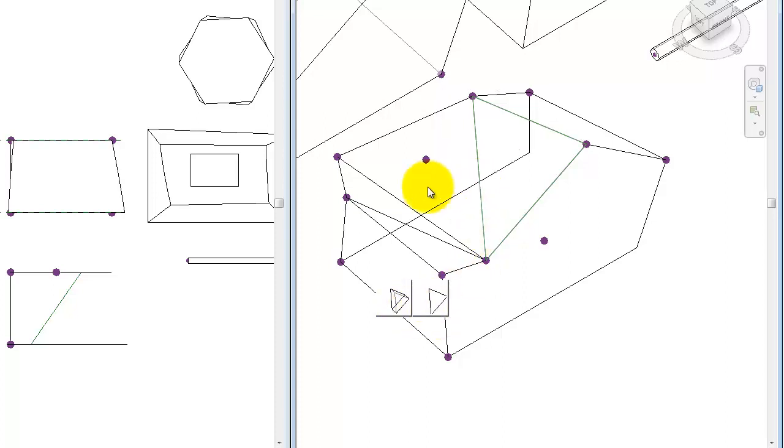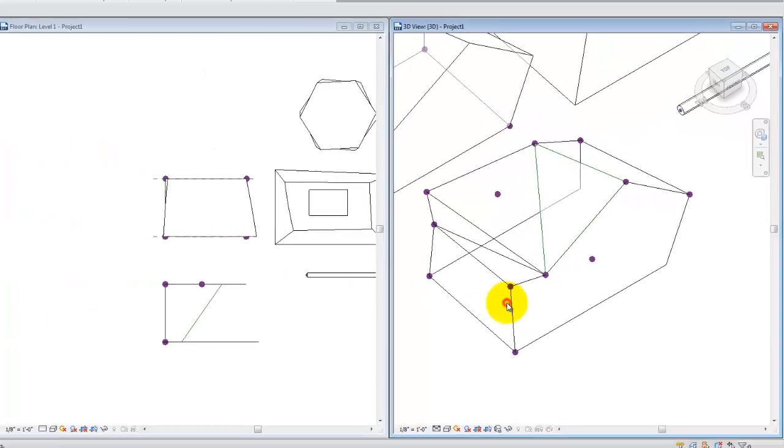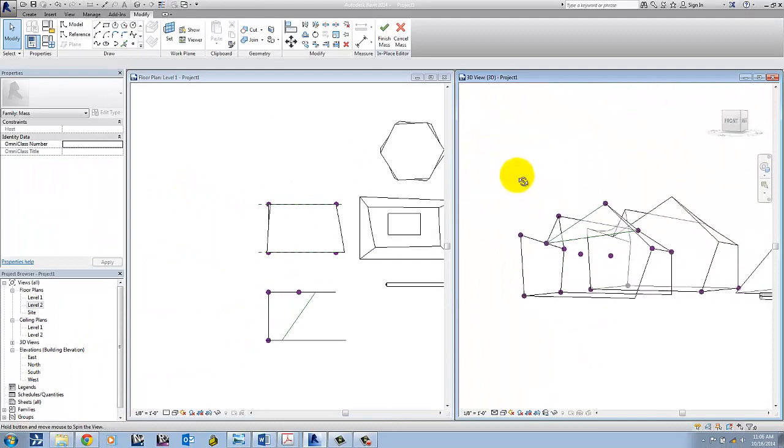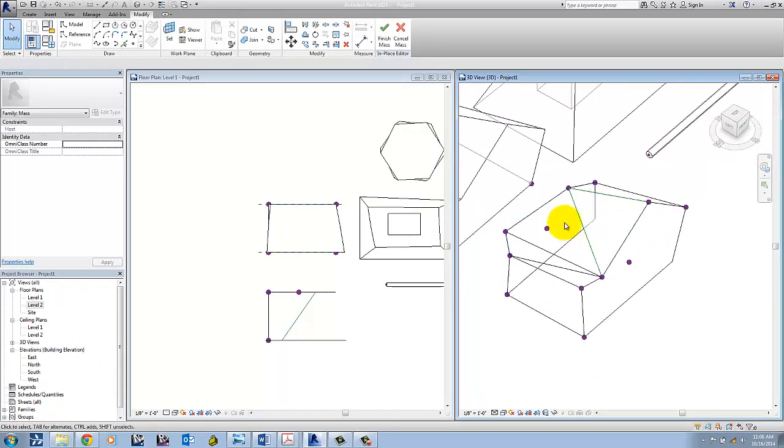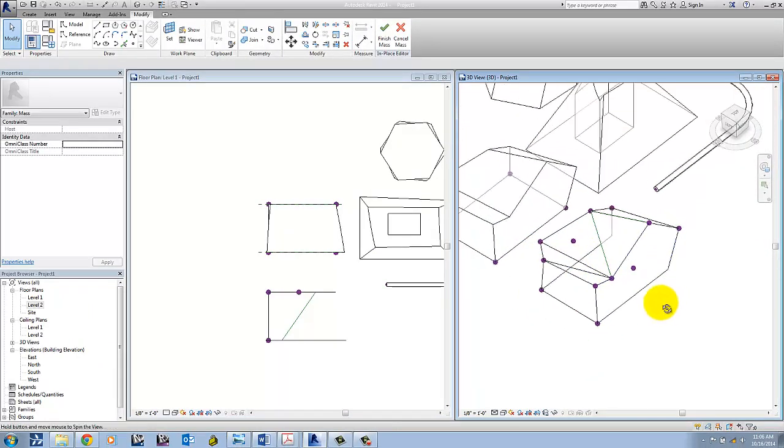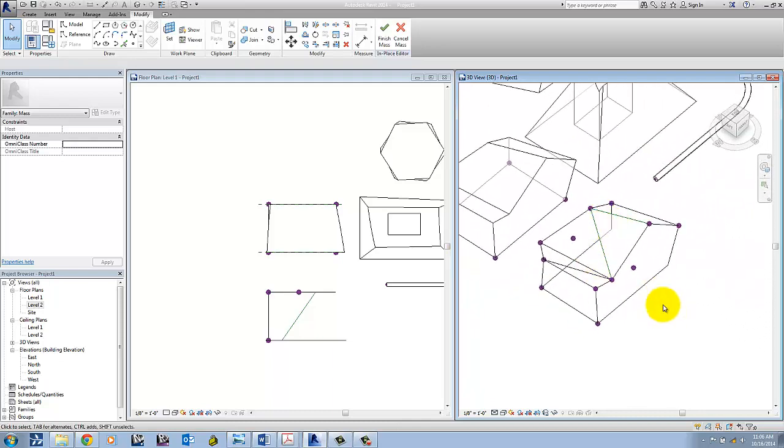When Revit does that, it'll give you the option to pick. So it created these 2 little boxes right here with a little preview of the 2 different options, create an extrusion or create a flat face. And then depending on which one you want to do, you just select it. There you go. So it created a surface. So I could go through here and create surfaces the way that I want it to do.